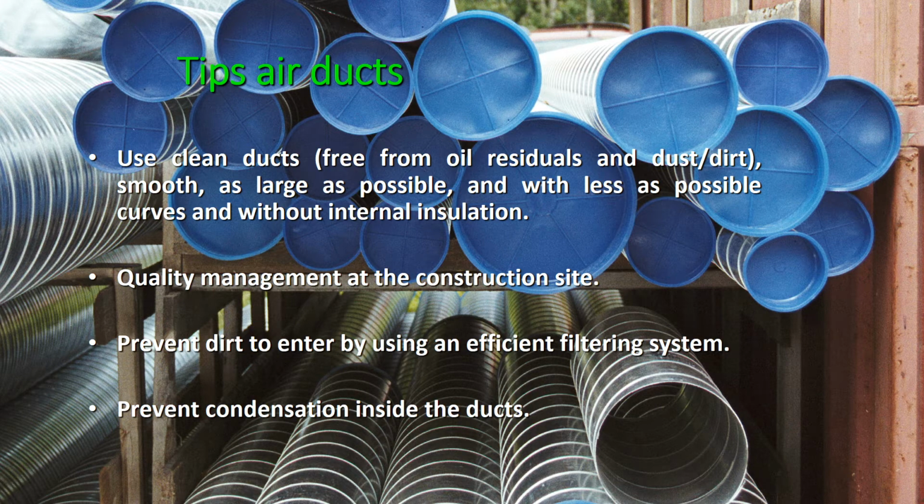To prevent dust and dirt from entering the ducts during operation, it is important to use an efficient filtering system. Furthermore, add insulation material to the outside of the duct, not on the inside, to prevent condensation on the inside and thus give microorganisms no chance. Also prevent condensation of water from humidifiers, and preferably, do not use sound attenuators. Those can become an important pollution source as well.